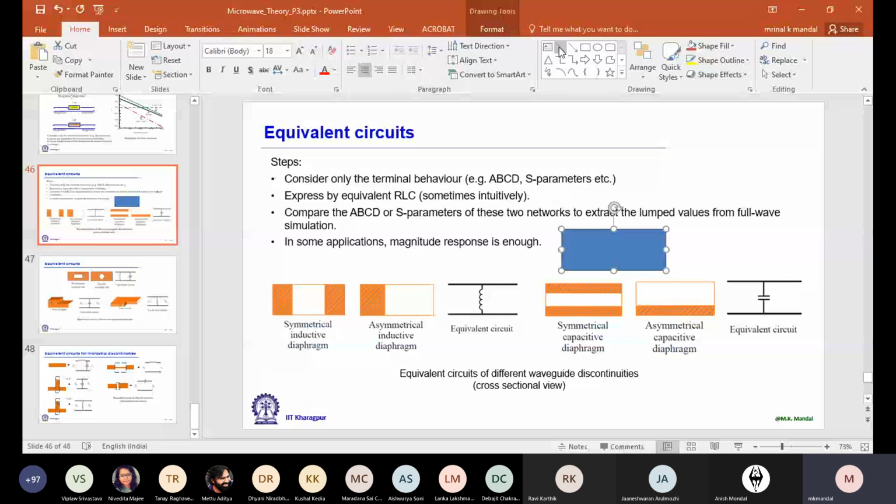I am considering a different situation now. What I represented here is actually a small metal plate inserted here, and we have a gap. So we don't have any cutoff frequency or anything like that, because it is simply a perturbation. Let's say the thickness of this metal part is 0.5 millimeter. So it is a section of waveguide of length 0.5 millimeter, which is basically nothing. We can't model it by a guiding structure. Better we model it by its equivalent model.